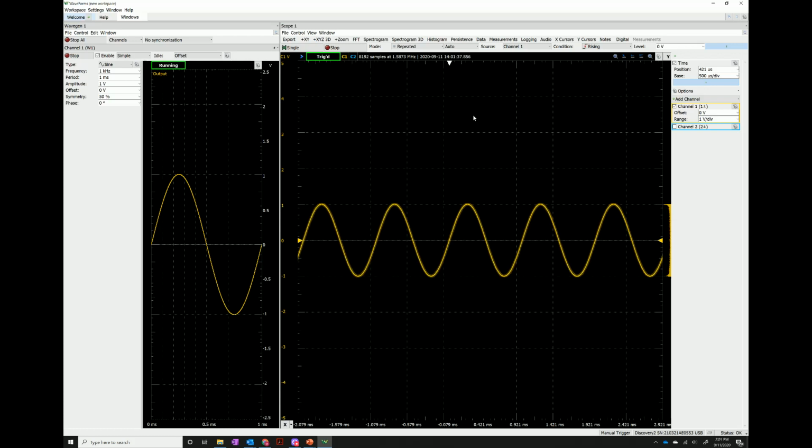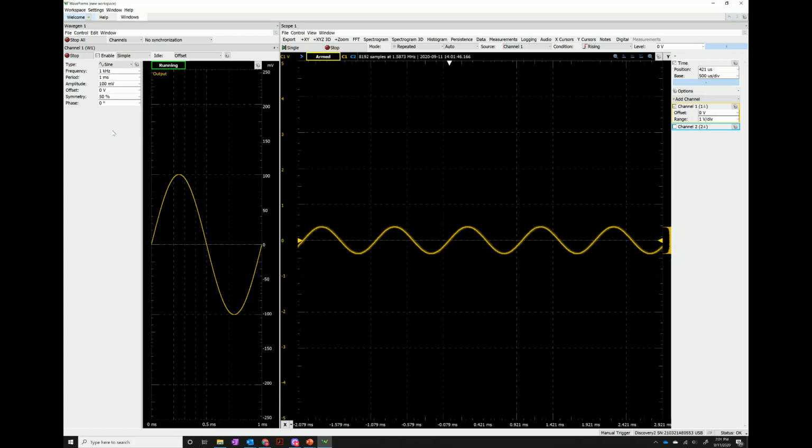If we go in and change our signal's amplitude of the actual transmitted signal from 1 volt to, say, 100 millivolts, we can see that our preview changes. And we get this range here, and we can actually see that our observed signal on our scope is updated as well. Right? In our scope here, we see that our amplitude is reduced, but we've kept that same resolution from before as 1 volt per division. Right? So we're still observing with the same resolution, but the signal, the actual generated signal, has reduced its amplitude. So it's a bit harder for us to see this signal here.